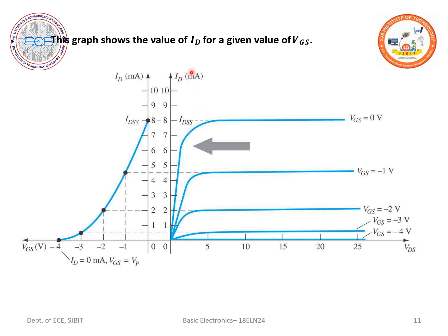So when we look into the transfer characteristic curve of the N-channel JFET, as and when my VGS is going negative, my current IDS is decreasing. Whenever my VGS is equal to 0 volt, I can expect my IDS to be maximum.